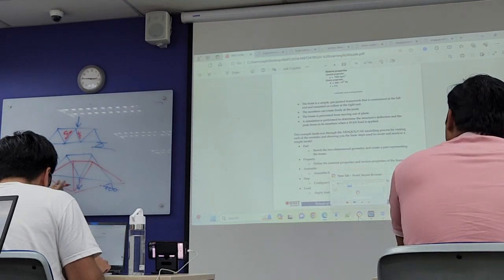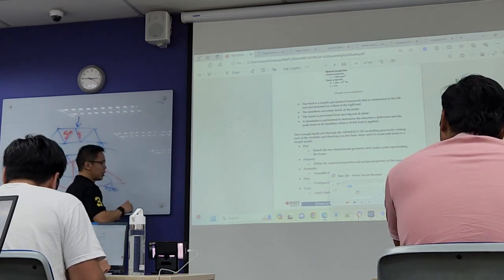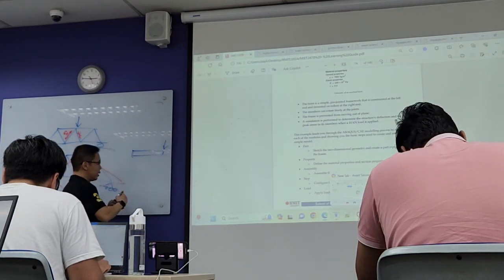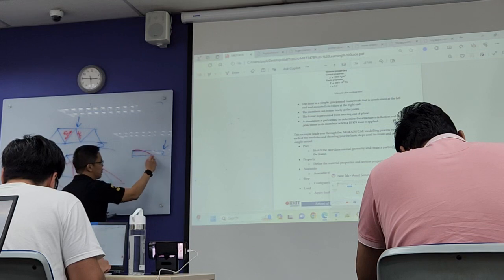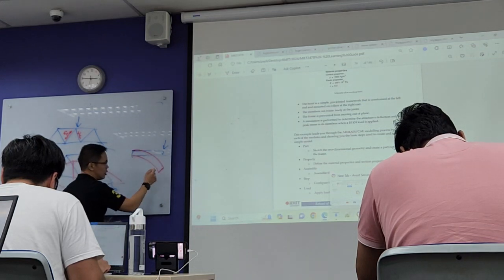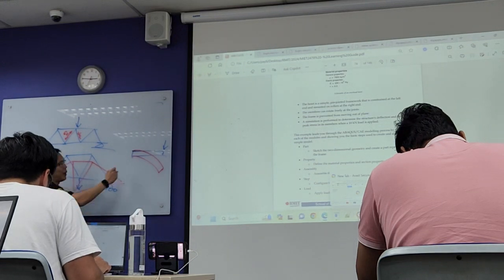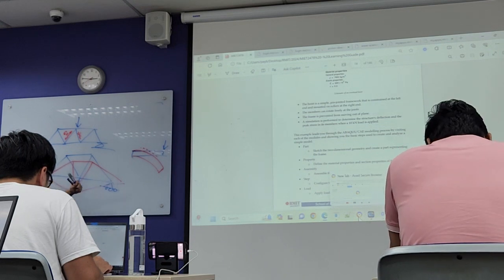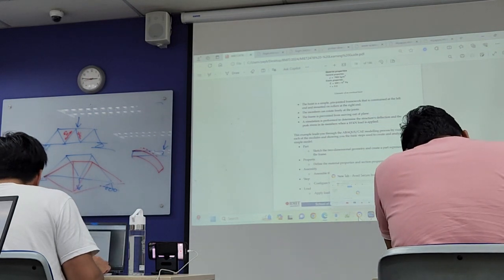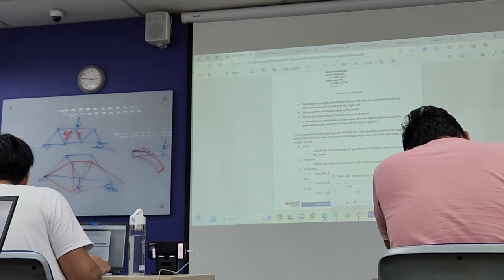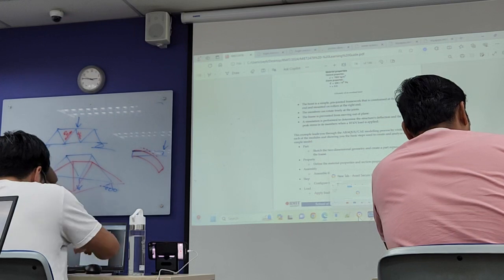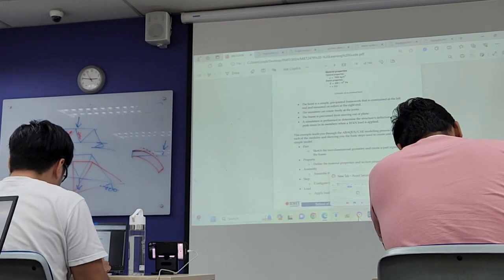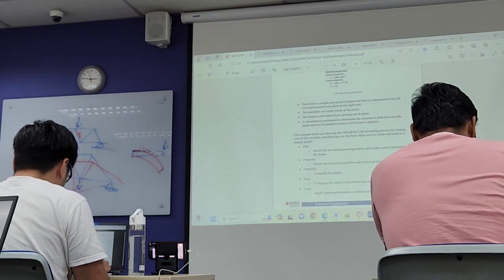That's all. Okay. Unlike just now when we said the beam, let's say for a continuum beam, when you have a load, it will have a bending. Alright, you have a bending, you see a bending gradient here. But here no. You don't see any bending, you don't see twisting, you only see elongate or compress. Okay? So that's the difference in the truss. And we say that in the truss you only have one stress, so it's the longitudinal stress of each member. So that's the main difference in the truss.